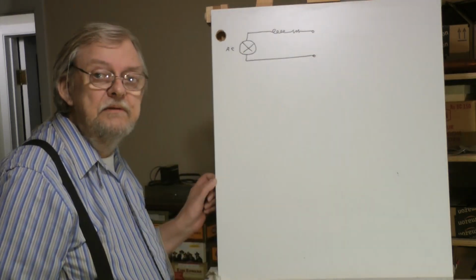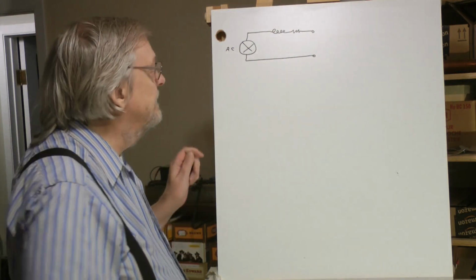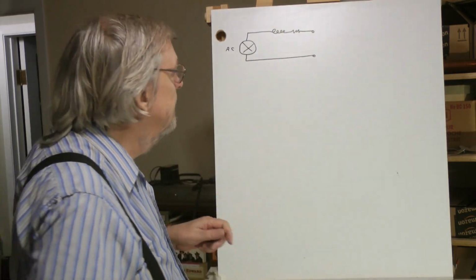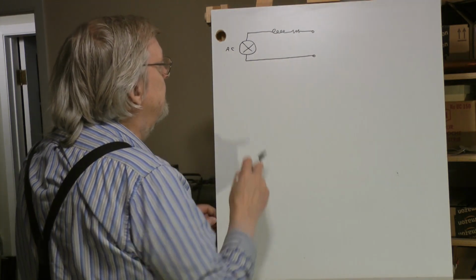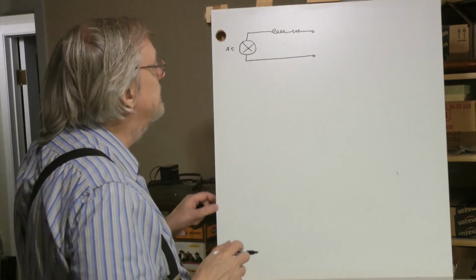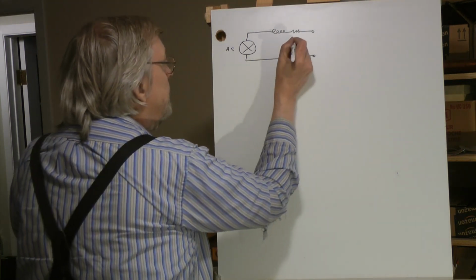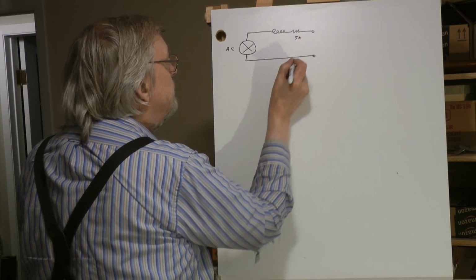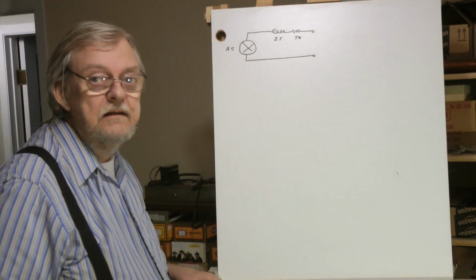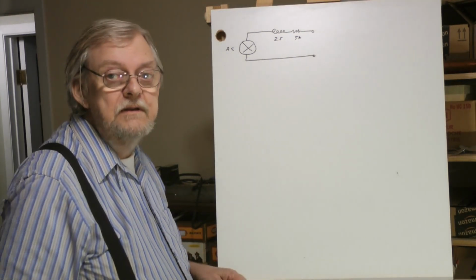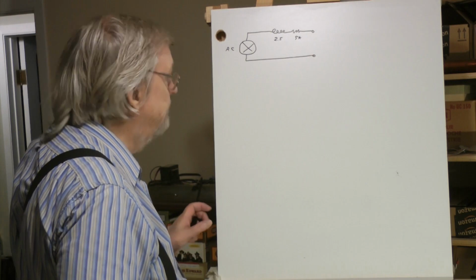There's a bit of capacitance, but it's really too small to notice, unless of course you turn your tone control off. That's a capacitor outside the pickup. We're not going to look at that. Since it's a low Q circuit, they always put the coil in series with the resistor, even though it's one part. From an engineering standpoint, it's two parts. You've got the 5K ohm resistor, and a typical single coil pickup for like a Tele or something would be 2.5 henries. That's quite a bit of inductance. You might have like 8,000 turns of wire inside that thing.